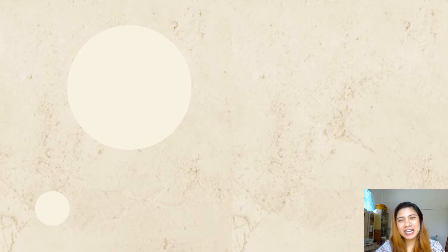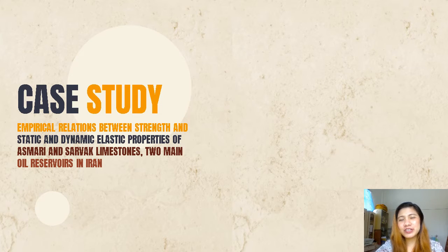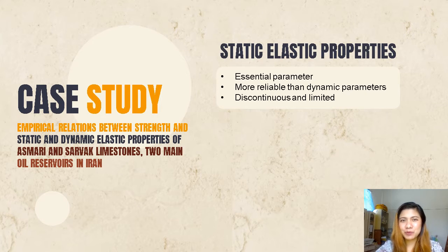Before we enter the next topic, I would like to share a research by Najibi et al. on the relationships of static and dynamic elastic properties. They mentioned that static elastic properties are the most essential parameter for any reservoir geomechanical modeling and more reliable than dynamic parameters. Hence, it is widely accepted in the geomechanics aspect.